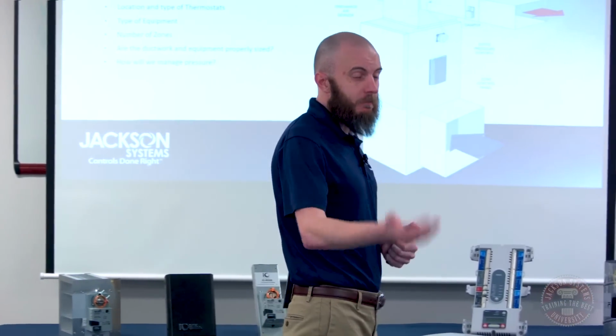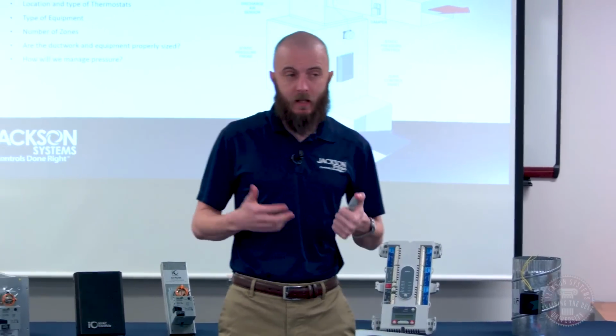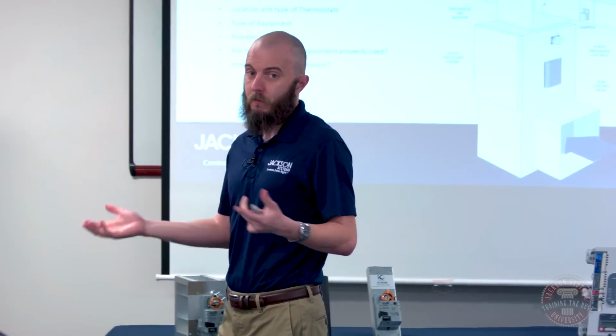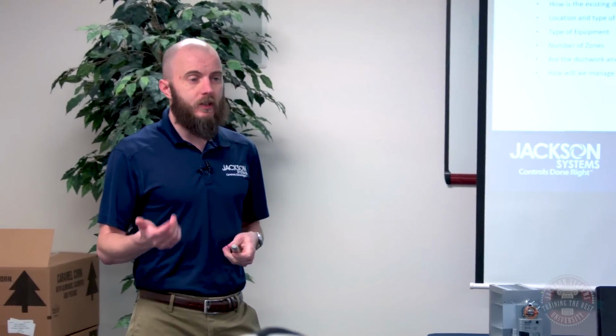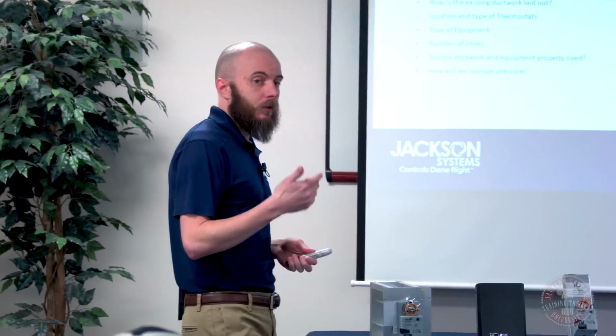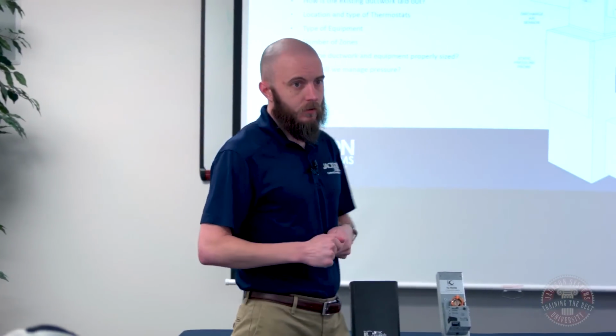So if you have a heat pump system, you're probably going to need to get a panel that makes sure it's compatible with heat pump systems. If you have a multi-stage system, you'll need to make sure you have a zone panel compatible with multi-stage systems.